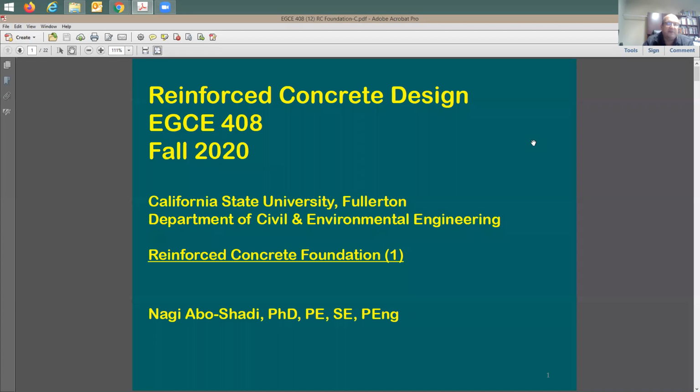So the first problem here is going to be how to come up with the size of the foundation or the pad. Size meaning length by width. Second problem is going to be the thickness and the reinforcing, the concrete strength, and so forth. Are you guys here with me? So we're going to have here two issues. One of them is how to size the footing. The second one, how to size the reinforcing and the thickness and everything inside the footing itself.